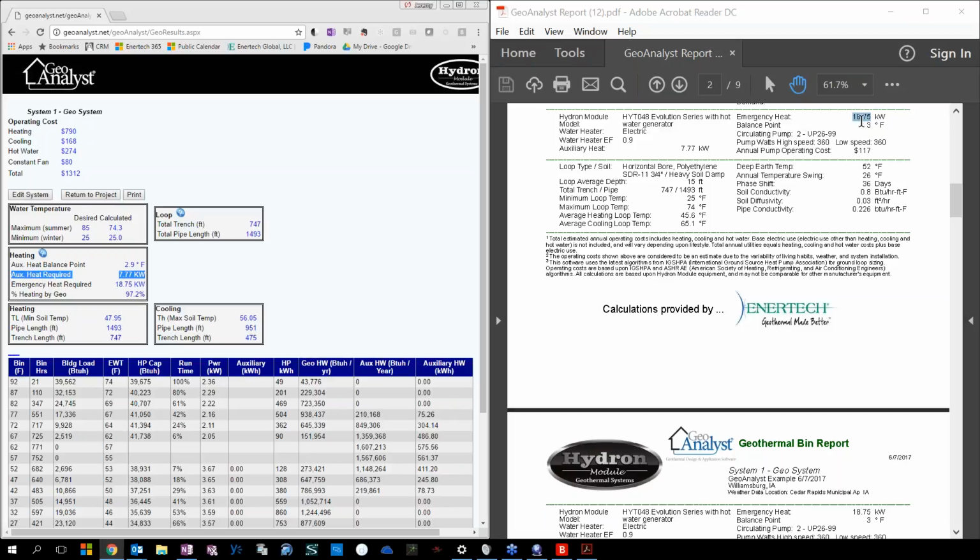The reason I'm saying this is because we don't have a tax credit, and if guys are still out there quoting projects that are 6-ton units with 20 kW heaters, they're probably not going to sell them because that's another $10,000 just for the Geo system, and you may have to force an electric upgrade to provide the 20 kilowatt supplemental heater.